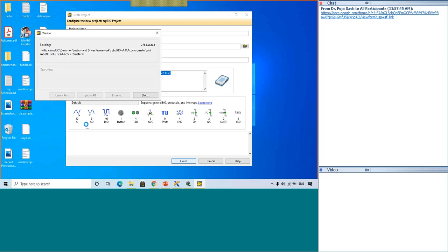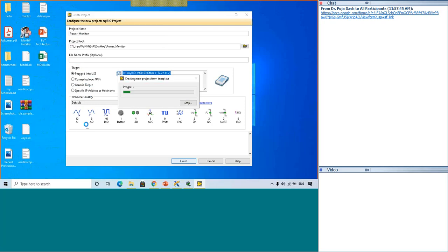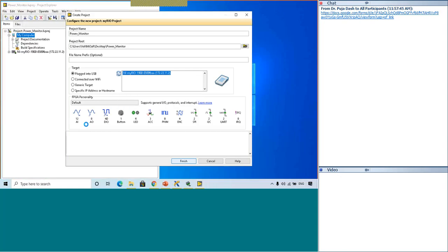There are several types of circuits which can be designed, with isolation, to convert that level of high voltage to a low voltage that can be subjected to acquisition. But instead of doing that, you have a separate card which is already developed, already tested, and already certified by a third party company that this is working fine. And several companies also use it.